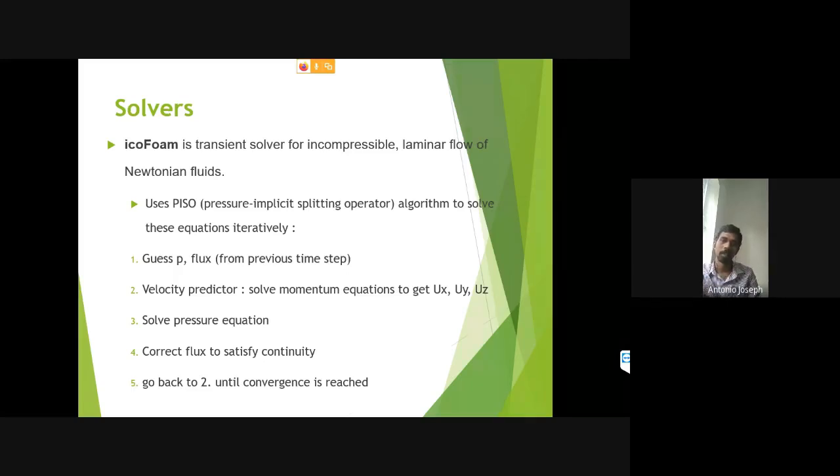The convergence means it will be comparing with the previous value for getting the errors. And the error is huge here. This process goes on until it meets the convergence. Convergence can be some error value. We can give the limit as 10 raised to minus 3 or 10 raised to minus 6. So if the difference between the current value and the previous value is within this limit, below 10 raised to minus 6, then we can tell that convergence is occurring.